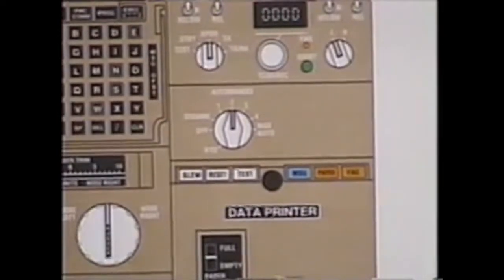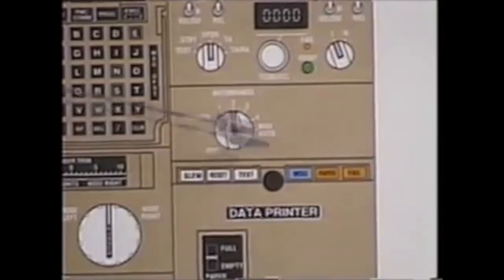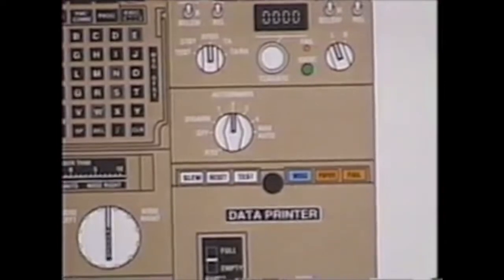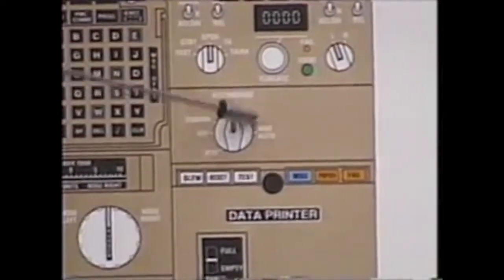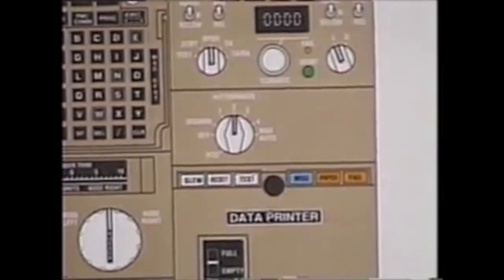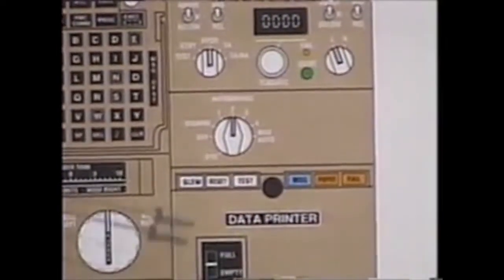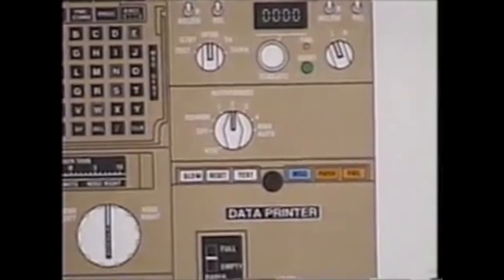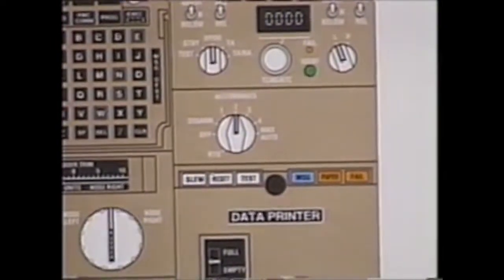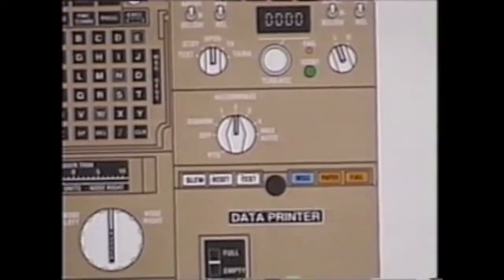If the auto brakes are not armed at touchdown, please do not attempt to reach up and arm them. You can physically outbrake the max auto position. You cannot outbrake RTO. Auto brakes will work on a normal brake system, hydraulic system 4. Auto brakes do not know that the alternate brake system exists.